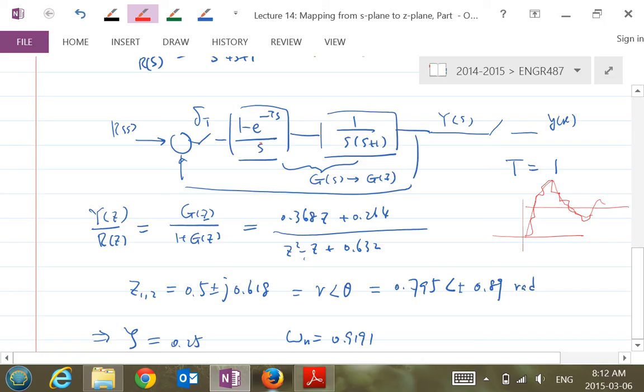Remember the zero-order hold, when we talked about numerical equivalency, I mentioned that the zero-order hold introduces a half sampling time delay. So when you introduce a delay, basically you're introducing a phase delay here. And in the control system, everything is basically about the phase. If there's too much phase delay, then the control system will become unstable.